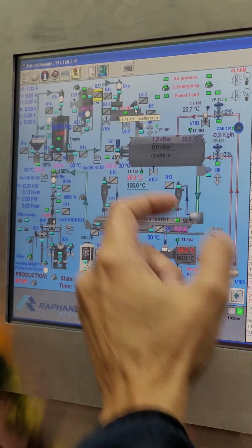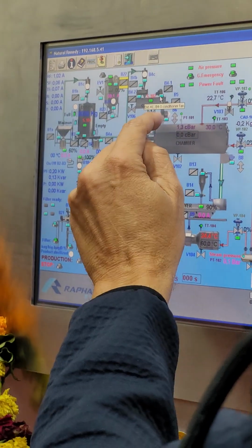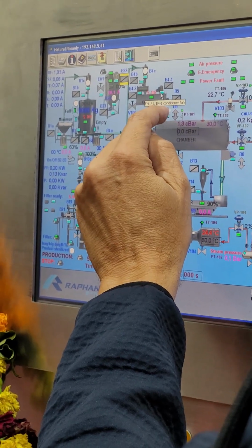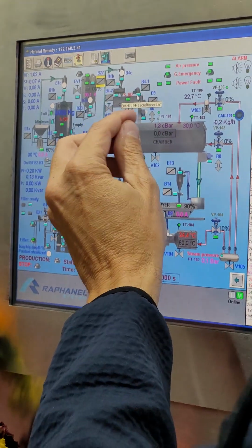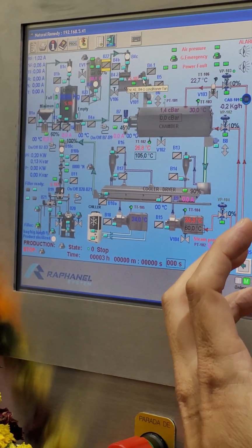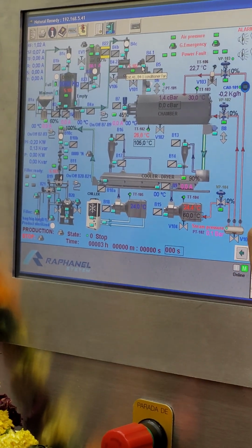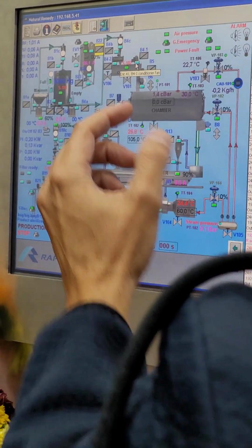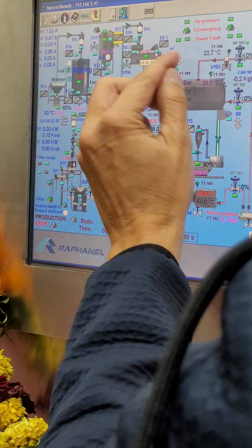For example, you are in production, working for 2 hours. Material blocks, where? Here? Here. The rotary valve is blocked. If the rotary valve is not blocked, and the material is blocked just above the rotary valve, then the material is blocked in the screw.